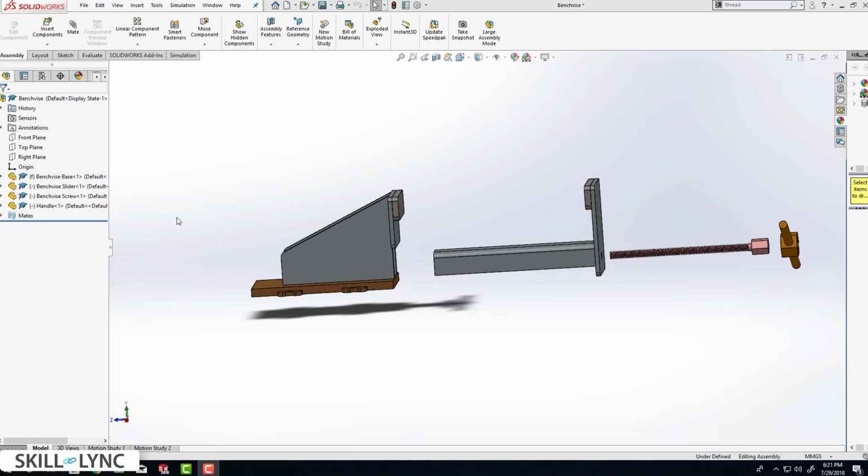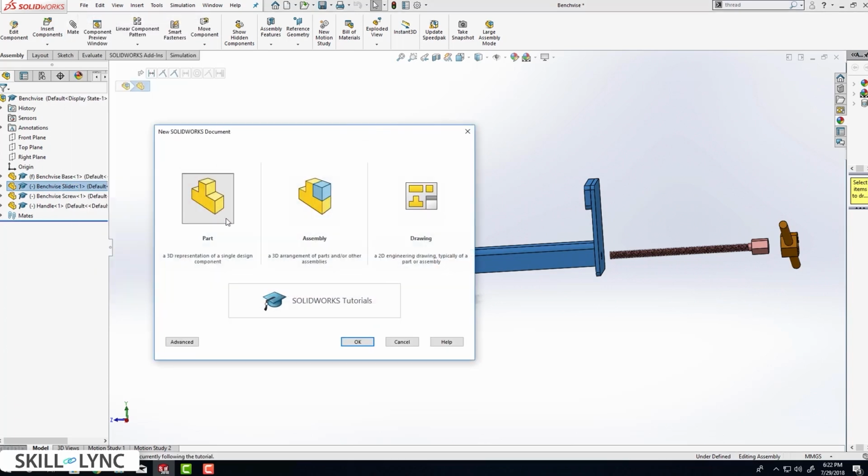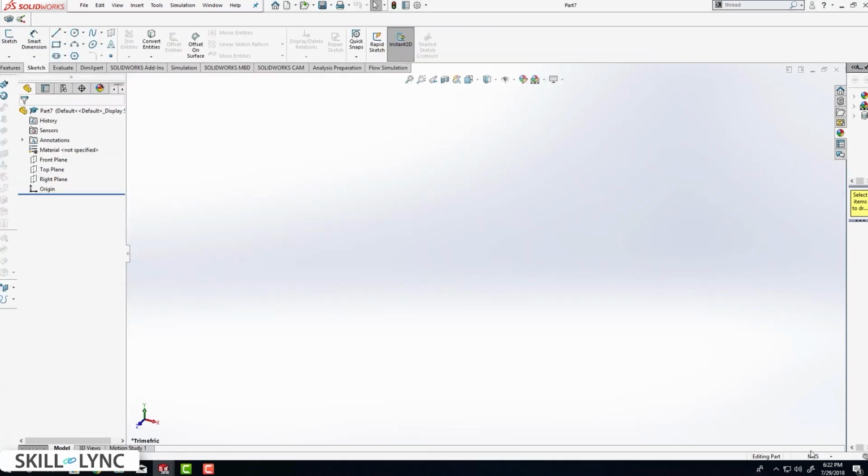In this video, you will be learning how to model the sliding jaw and the associated components. So this right here is the slider connector which will be mounted with the moving jaw. So click on File, New, Part to get started. Next, we are going to be checking our unit system as usual and change it to millimeters.